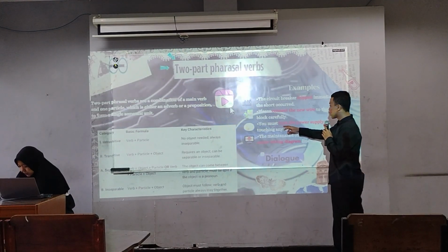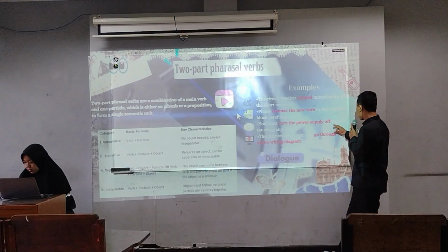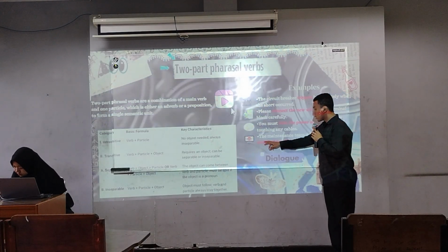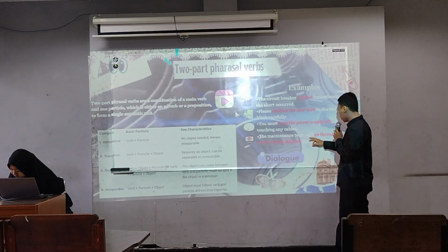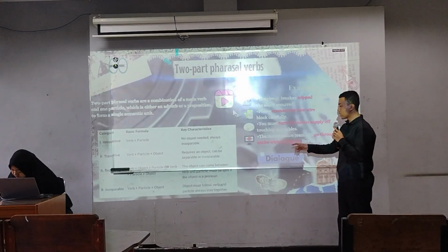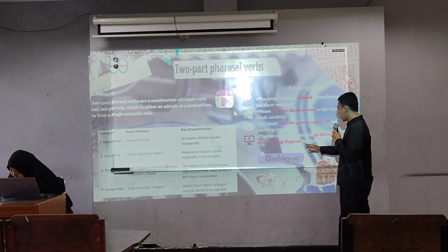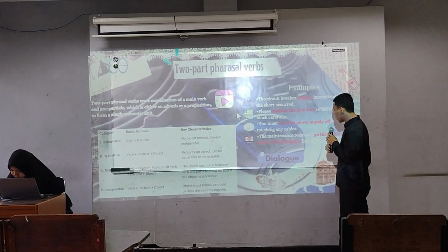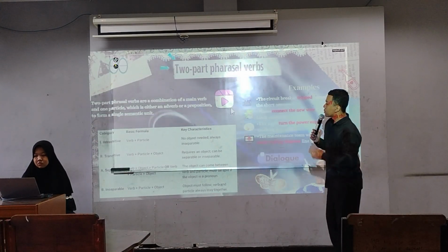And three, you must turn the power supply off before touching any cable. And last, the maintenance team will go through the entire wiring diagram.